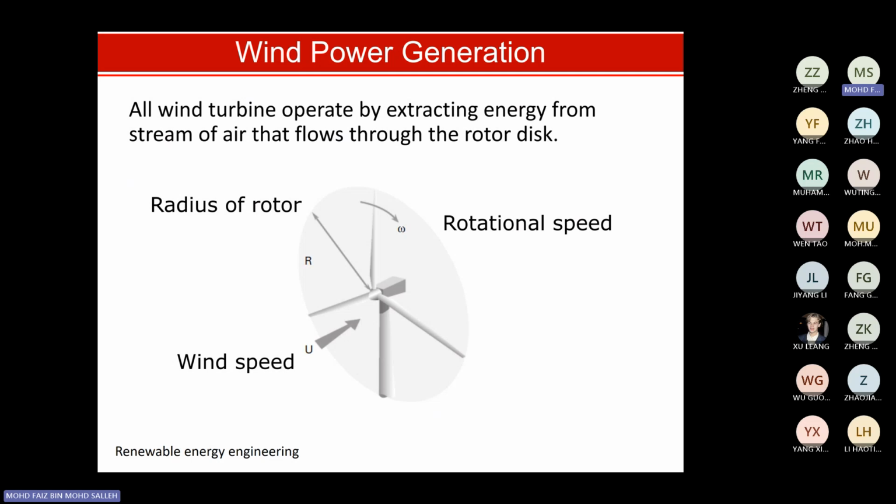For this case, if you remember, we have the so-called Betz limit, meaning that we cannot convert all the flow or the kinetic energy of air into electrical energy 100%. We have a limitation which is around 58 to 59%. If you could convert 100%, it would mean that all particles of the air would be stopped at the turbine, which is not possible. So you have a limitation of around 58 to 59%.